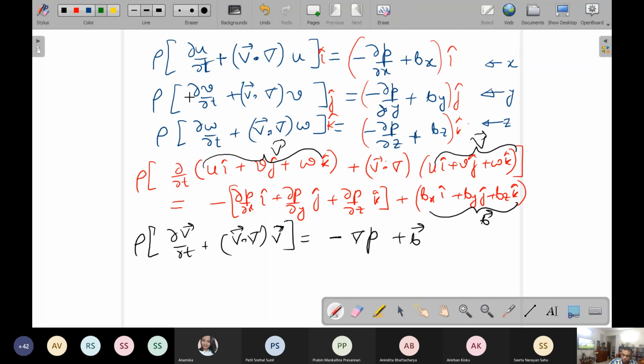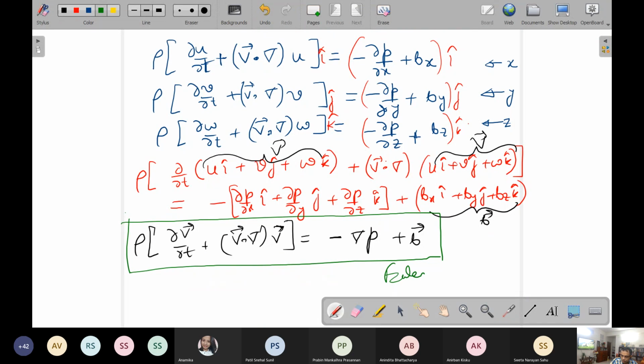Okay. So this is Euler equation. So the only restriction of the Euler equation is that it is inviscid. There is no other restriction related to this. So this is quite a general equation. On the face, it appears to be very restrictive because it is considering inviscid flow, and many of us have an intuitive feel that there is no such flow which behaves like inviscid flow.